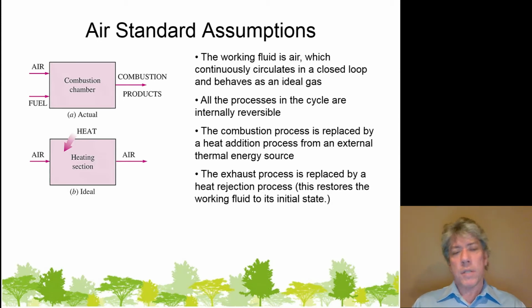Well, there's a couple of reasons. If you think about the air and the fuel mixture, there's more air than there is fuel by quite a bit, right? 14 to 1 or so. In the case of a gasoline engine, there's 14 times more the mass of air than fuel. So the main thing coming out in the combustion products is really the nitrogen that came in. I mean, after all, air is the biggest thing, in terms of mass, that comes in, and the air is 79% nitrogen, so the main thing coming out in the combustion products is hot nitrogen.